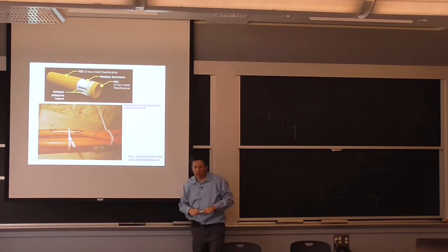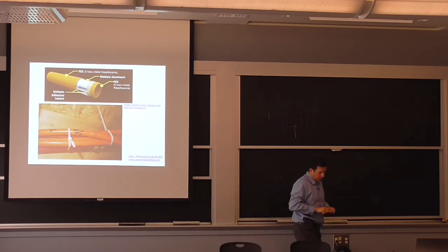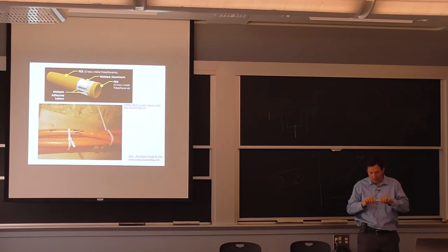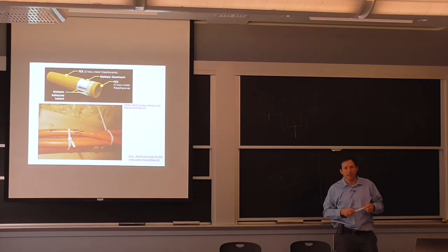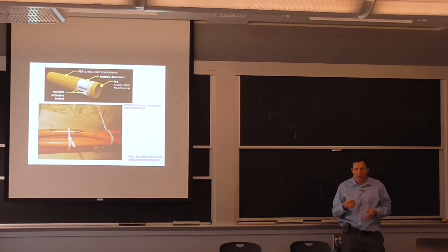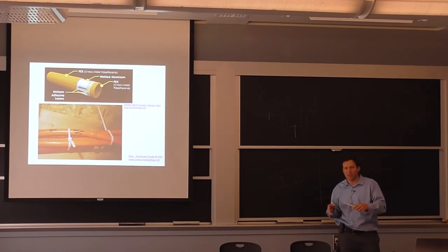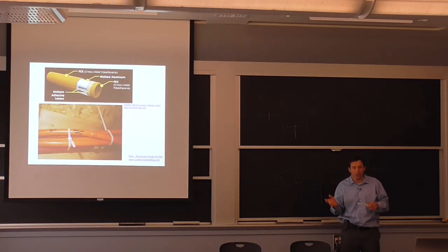But what really happens is, this is the same material here. And it's the very inside part of the material that didn't have enough antioxidant. This is a whole production that went through a lot of homes, and they did not have enough antioxidant on the inside layer to be used with potable water. So this is where you start talking about, okay, I have this pipe and it will work well for a heating system, because in the heating system, I have oxygen at the beginning and then I circulate and there's no more oxygen. But if I use potable water, there's always oxygen coming in, and then I'm going to degrade the polymer a lot faster.